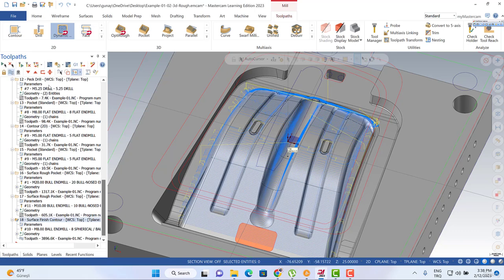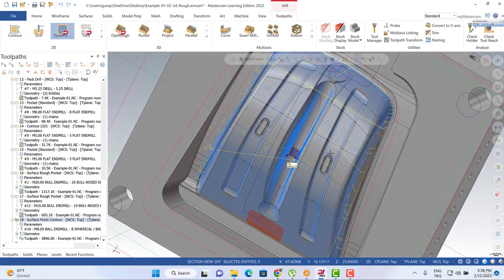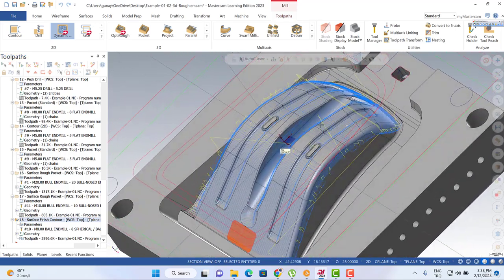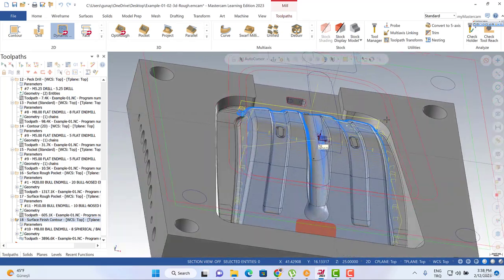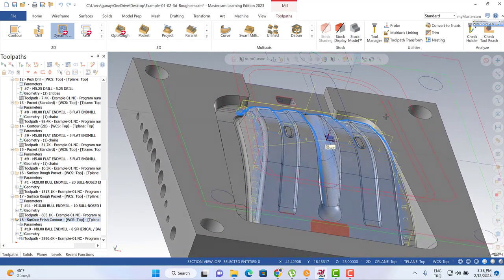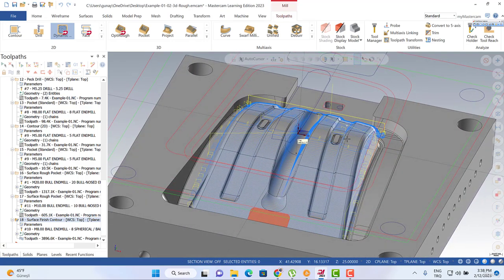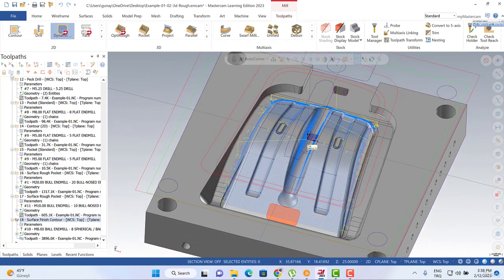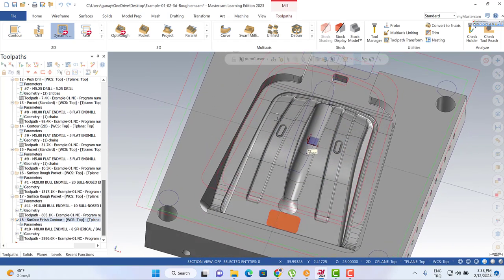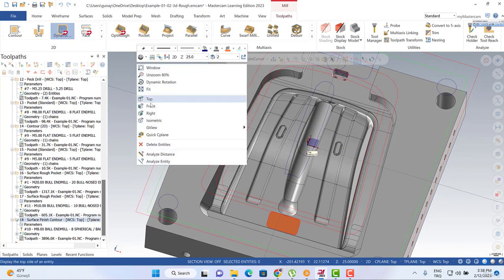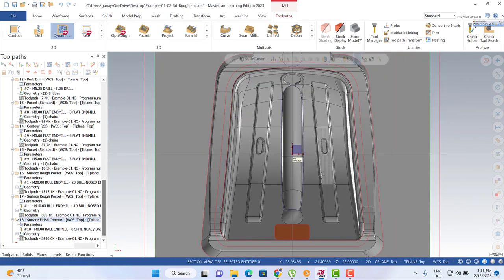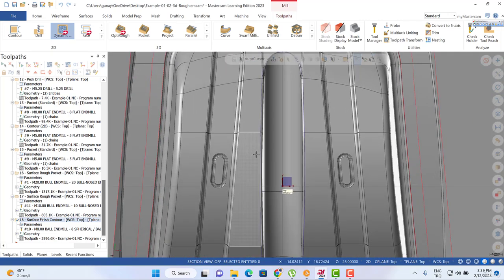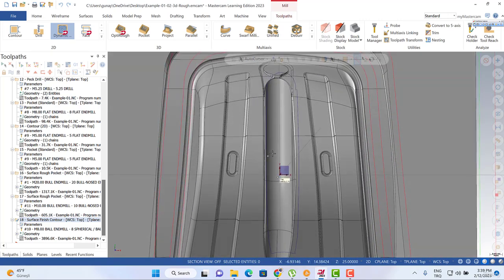Yeah, that's okay. And when we turn to here, we're going to see that kind of toolpath. So that's cool. That can also be used as a semi-finishing process, so that's quite important for our process. Okay, anyway, after that, we can easily create our scallop toolpath. So when we consider our scallop toolpath, maybe we should create an extra boundary for here.